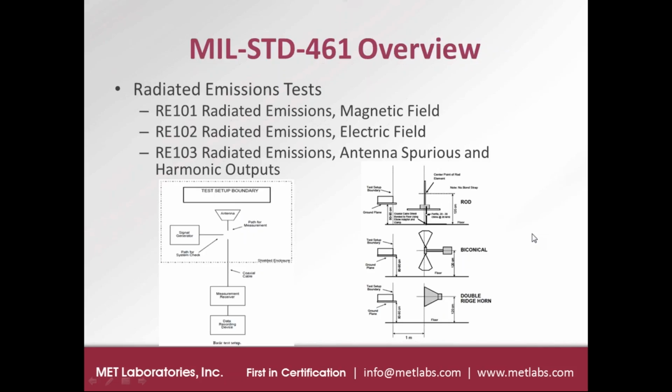And then the diagram on the right side shows some of the various antennas that are used to get through the entire frequency range of the RE102 test. There are very specific setup requirements for those, such as the height off the ground plane and other parameters, such as the measurement point on the antenna that's used to measure the height.